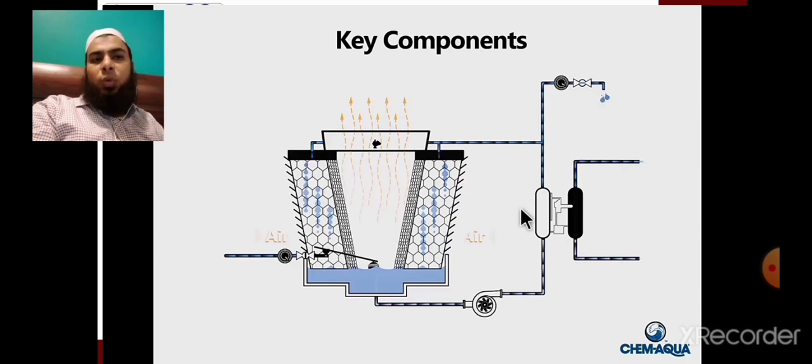If it is an air cooled chiller system, the condenser is cooled by 35 or 40 degrees centigrade surrounding air, but with a cooling tower it is cooled by 20 to 23 degrees centigrade. So you can imagine that the refrigerant gets cooled down very quickly, so the compressor doesn't need to run for a very long time.